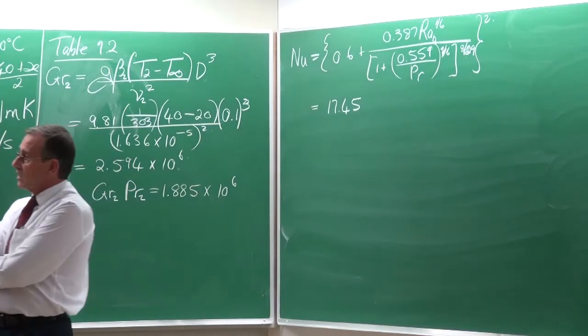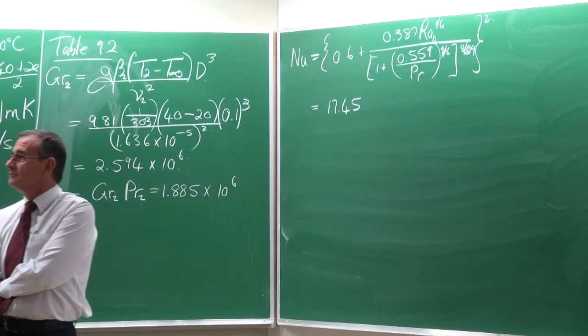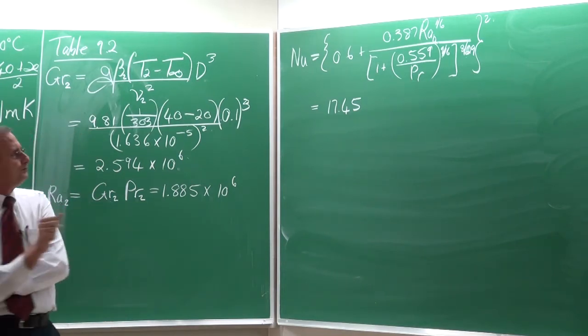Again, when you calculate something like that, always think about it. Does it make sense? Natural convection, yes. Up to 10, 20 values like that, but not normally thousands, not 10,000s. Also, it can't be smaller than 1. If you do that, then you must realize that you've made a mistake.